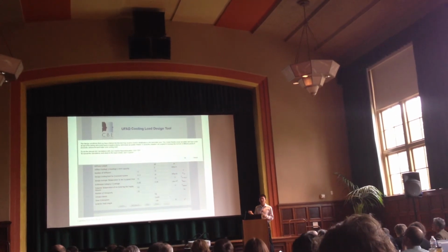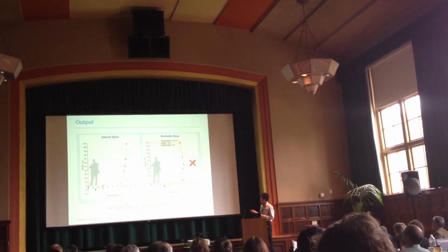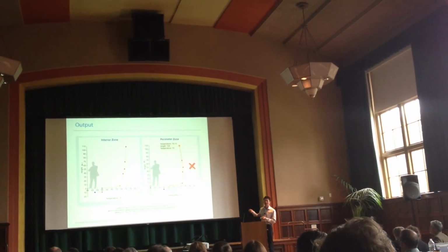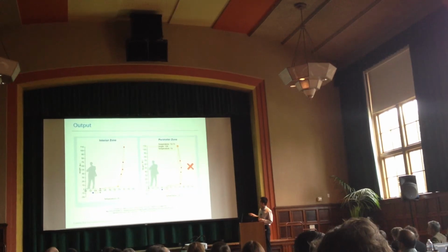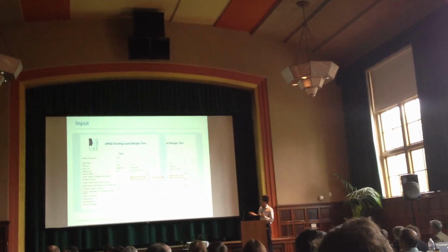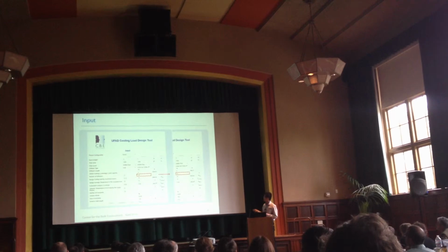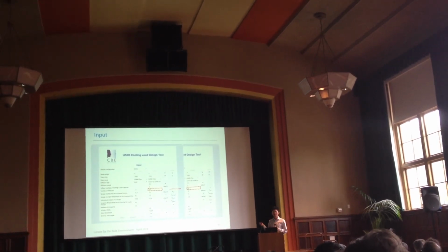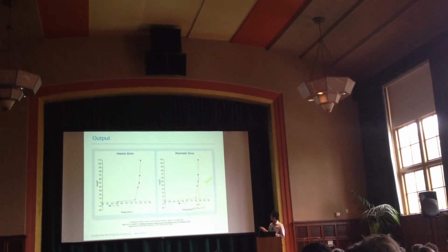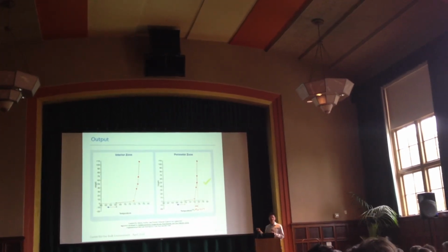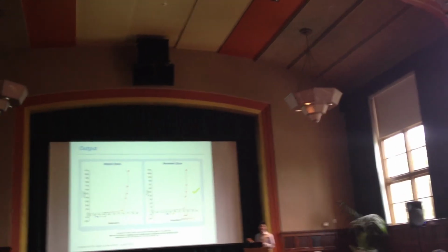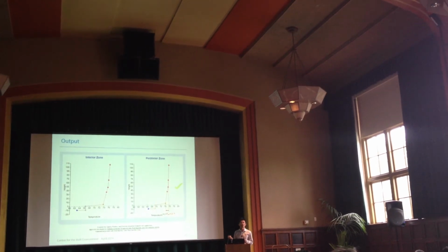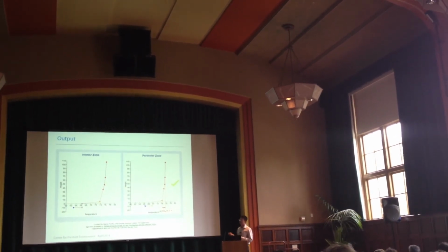So if we hit OK to see the calculation results, you're going to see this. Yes, in the perimeter zone, it does have this reverse stratification, and we don't want that. So from the feedback of the tool, we're going to increase the number of diffusers from 10 to 18 and see whether the problem will be solved. As it shows here, yes, we solved the problem, and we have 1.5 Fahrenheit degrees of stratification, which is not that bad in terms of the perimeter zone. So we fixed the problem in the perimeter zone.